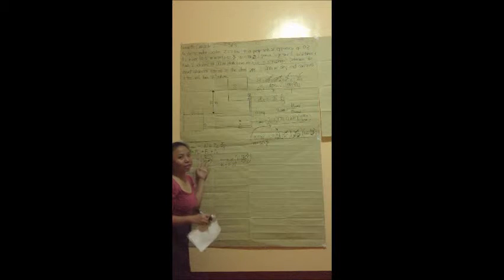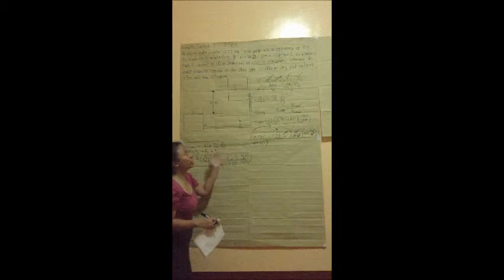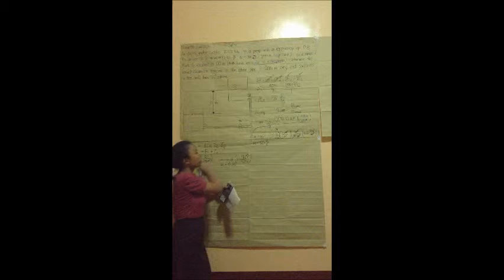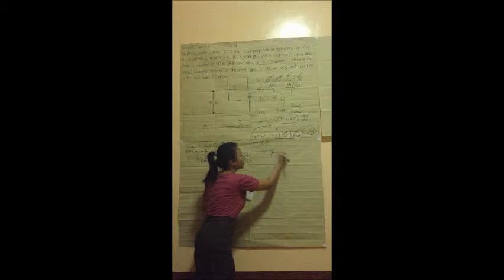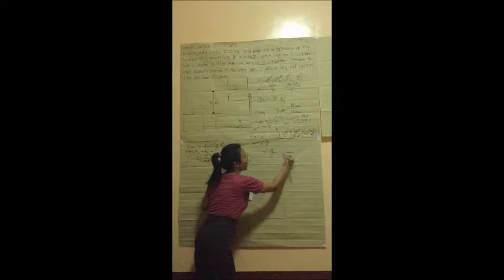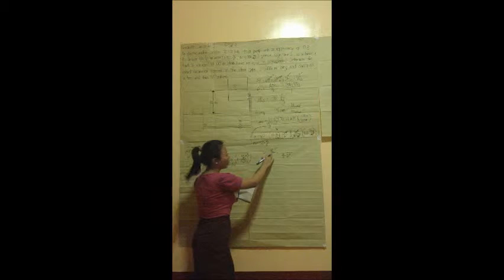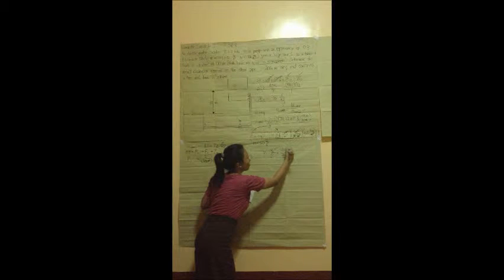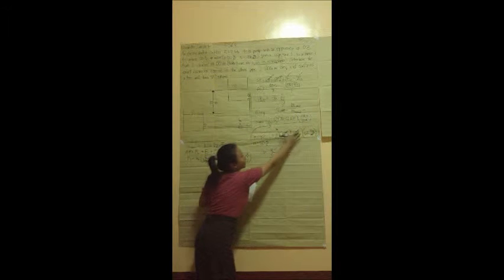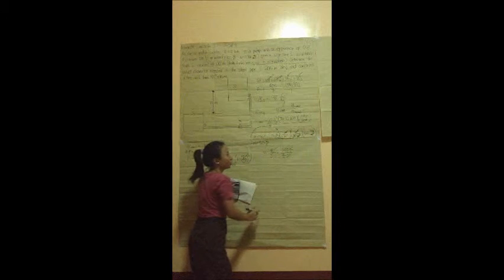Velocity changes when diameter changes. And since diameter is what is asked, we should represent V in terms of D. We can represent V in terms of D by using the formula V equals the volumetric flow rate over the area. And the volumetric rate is given, and the area we can represent as pi over 4 d squared. From this mass rate, we can say that the volumetric rate is 0.05 meter cube per second using these conversion factors until here.